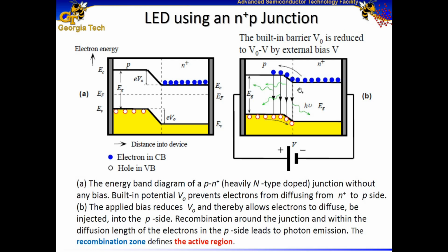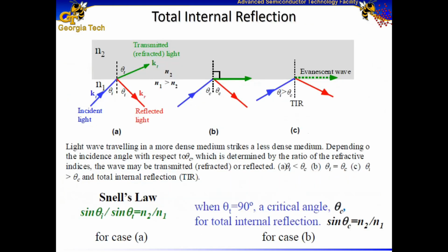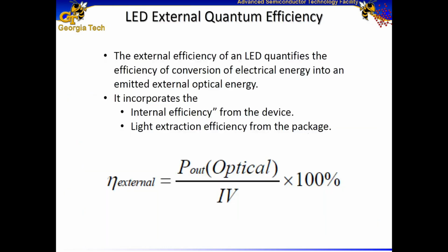Since we don't have high concentration of carriers to recombine, this kind of basic PN configuration light emitting diode structure would result in low intensity light. We would not have enough visible light for our purpose of interest. So we need to actually work on more complicated structures in order to achieve high intensity light.